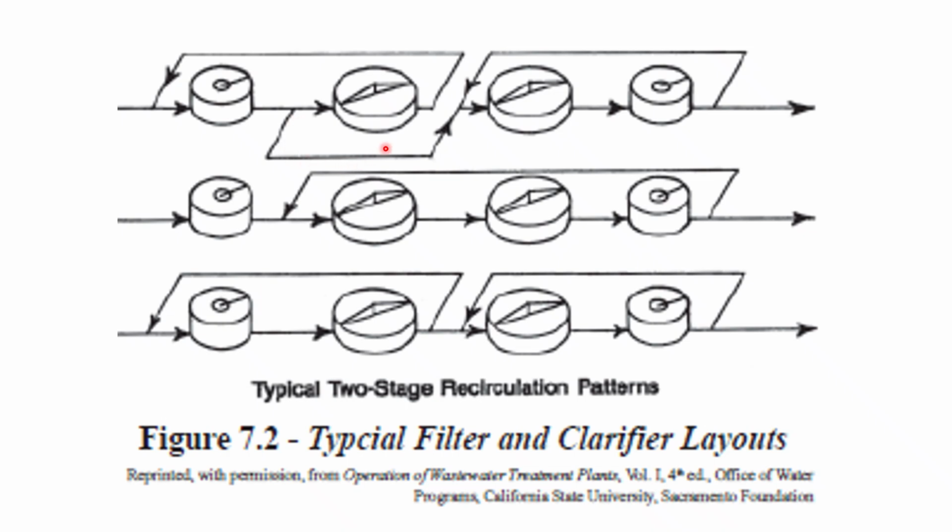So we send this primary effluent into a second trickling filter, okay, and it can go to a secondary clarifier, and then we're recirculating that here, okay. So we're doing a couple of things. We're removing suspended solids by recirculating it through the primary clarifier, and then we're getting more of the dissolved organic removal by recirculating from the secondary clarifier to the trickling filter.